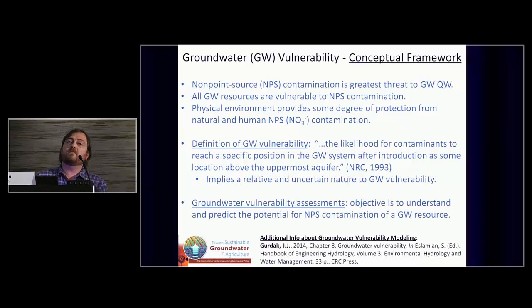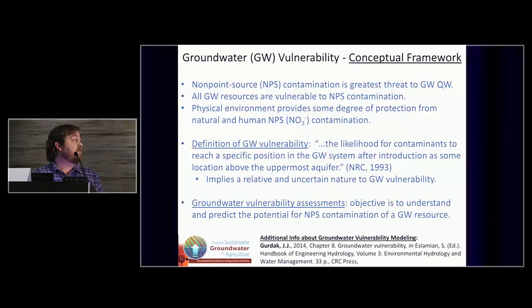So a definition of vulnerability that I use, there's many definitions out there. The one that I like to use is a few years old now from the NRC, but it's the likelihood for a contaminant to reach a specific position, and that's really important for these studies. We're going to focus on a specific part, the vertical component of the aquifer after those contaminants have been introduced, usually at land surface at the uppermost aquifer. So this definition, this framework really